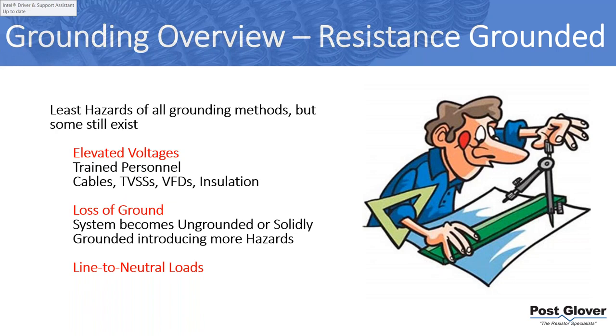So when you get a line to ground fault and you continue to operate with that, your original voltage of your three phases, individual line to ground, was 277. One of your phases is faulted, so the voltage is 0 on that phase. The other phases see an elevated voltage of 480. So we have elevated voltages on your two non-faulted phases. You need to worry about that.